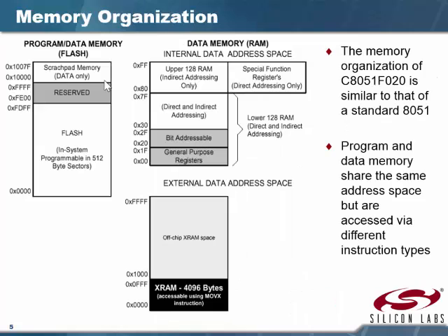Now as we look at our memory map here, this is for the 8F20. Ours is the 8F850. It's very much the same. Silicon Labs parts all use the same basic memory map. The only thing that differs is the size down here. Some of them have 8K of XRAM, some have 2K or 4K. This XRAM is memory that's on the chip,